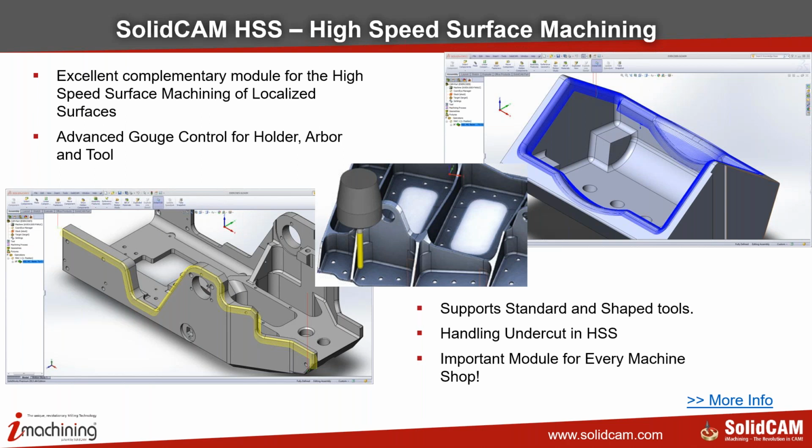Okay, local surfaces, very small areas, and you would like the tool to go around along the flow line. That's when HSS is used. It's an excellent complementary module for high-speed machining of localized surfaces. It has got complete control over holder, arbor, and the cutting side of the tool. It supports standard and shape tools.